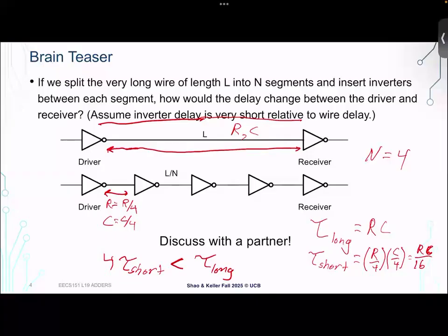There's an optimal length of wire paired with a buffer for a given process, where you balance the added delay from the inverter versus the shortened delay from cutting the wire into multiple pieces. So this is a classic analysis or optimization problem about wire segments, is how frequently to buffer them.